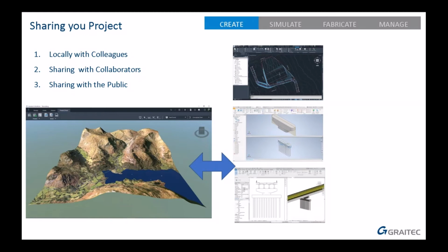So you can take it out of Infraworks, put it into Revit, mess about with Revit, put it back into Infraworks and link the two together. Same with civil models. You can just right-click, re-import, and it will go and find the original model, re-import it if there's been any changes in the original model, which is quite useful as well. Now remember, you can store your model on a server or in the cloud, and this opens you up to the BIM 360 collaboration tools. Anyone with access to the project will see your model.